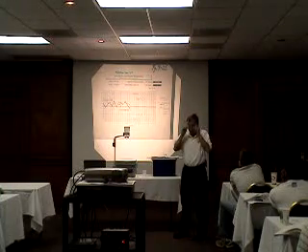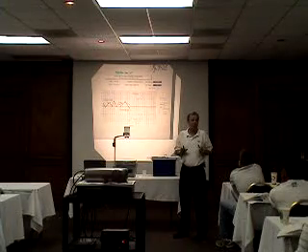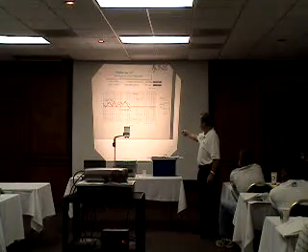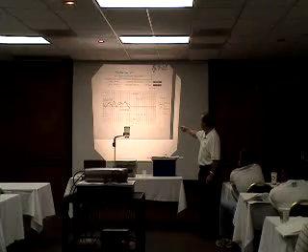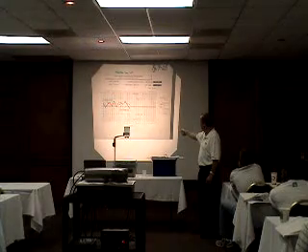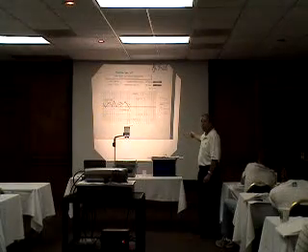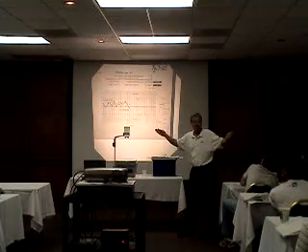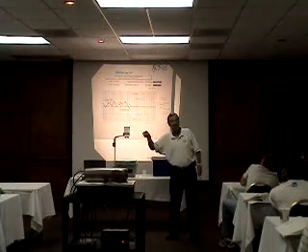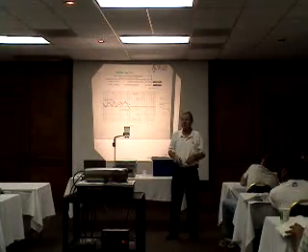To sort of give you a feel of what the specs are, this is very simplified, but basically the spec says to the contractor that if you'll keep your individual test, or your solid black line, inside the individual control limits, which is my dashed red line, and you'll keep your moving average, or your red line, inside the moving average limits, which is the green line, you read the spec. Very simplified. It's not written quite like that, but that's basically what it is. If you keep the individuals inside the individual, moving average inside the moving average, you keep running, you're going to get full pay. Basically what the spec says.